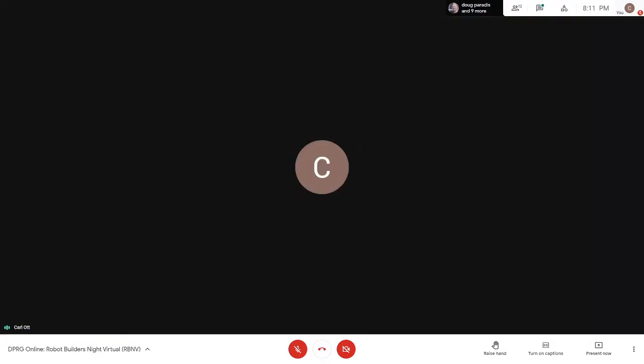Right. Yeah, I mean, going way back to the 80s when I was doing my first laser rangefinder with TTL 7400 series stuff, you had to make sure all the chips were powered up, because the chips would come out of reset at different thresholds as the power came up. Some would come out before others, and to get a clean reset, everything had to be powered up before you released the reset. So I had a separate chip to do that in the 80s in the discrete world.